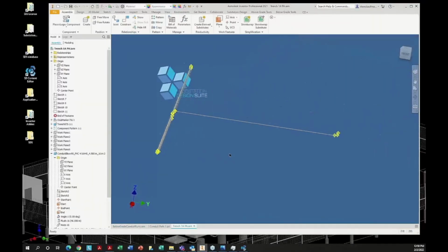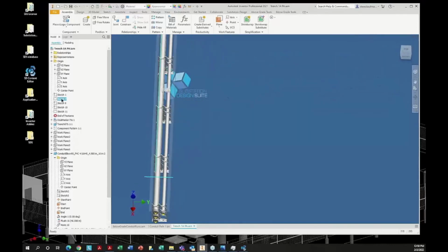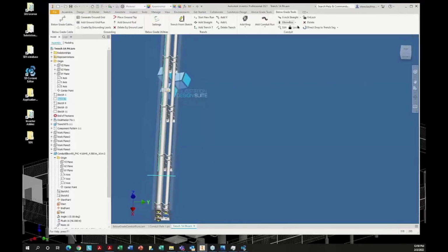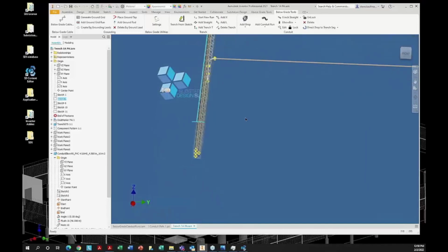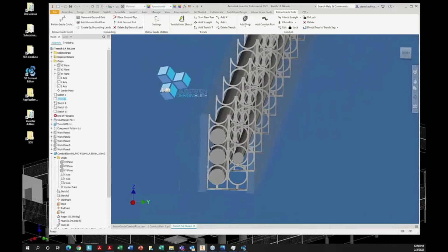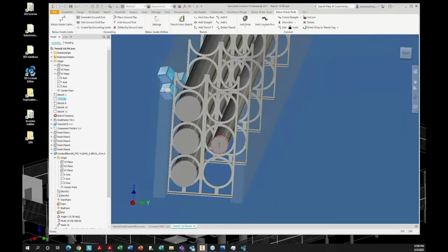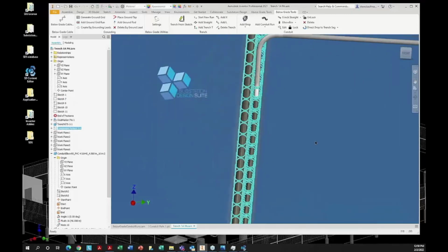So here's what I'm running here. I have my sketches in here, so I can do things. Here's my sketch for the runs. I'm using the auto route path only and at different depths. So I have my depths coming in to meet here. And I remember when I did this, I had to calculate what depth it was going to be, because I wanted it to show at the bottom of these supports. These are actual supports that they purchased. And I just patterned this through the support spacing.